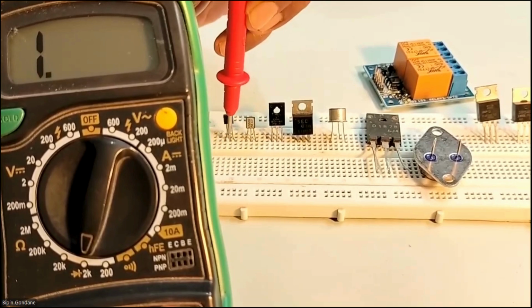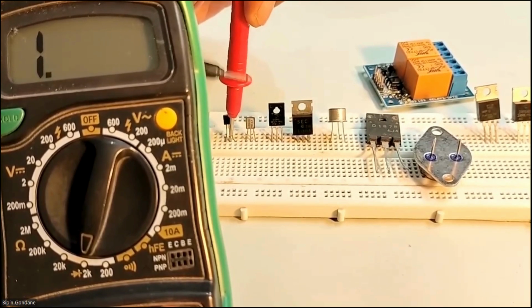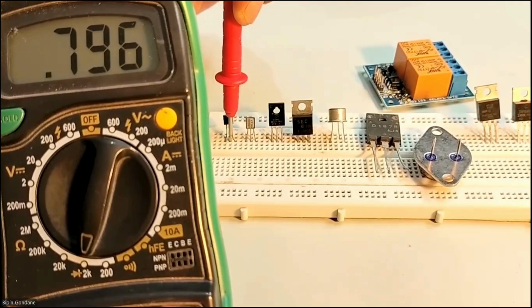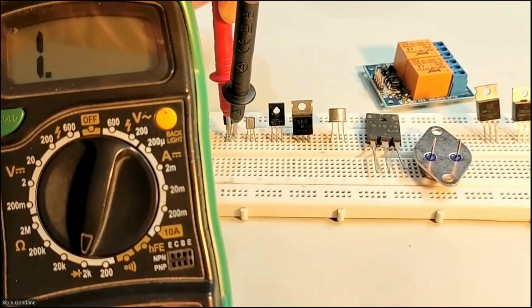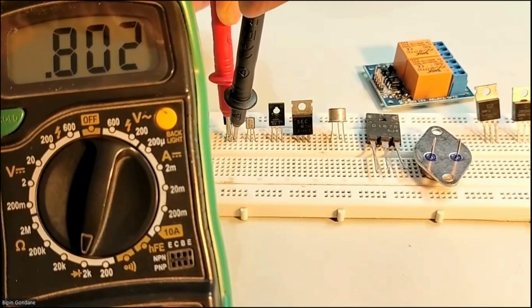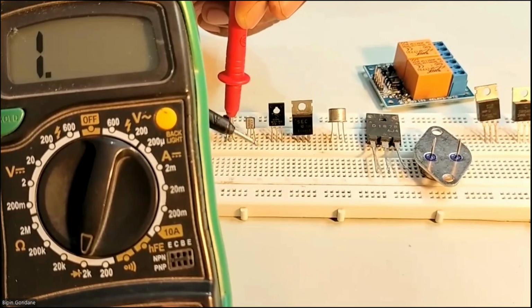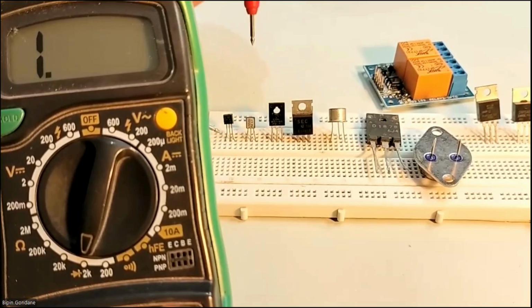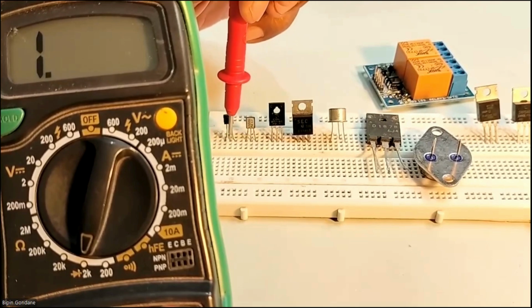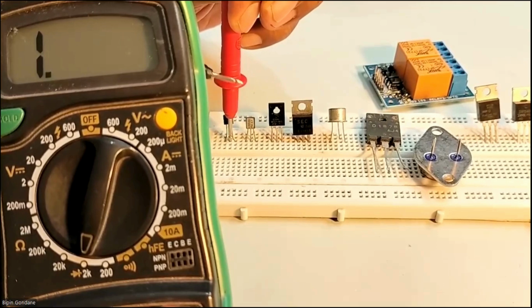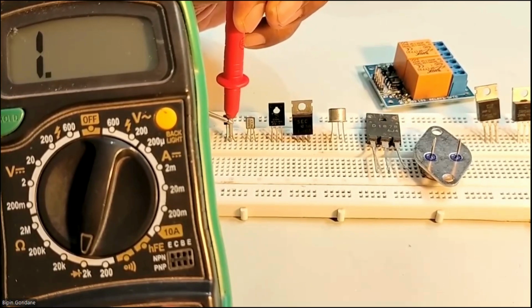When the positive end, this is positive, P, and this is negative, when it is kept here, we got the value. And the same thing happened on this side also. So what is this transistor and what are these points? Please remember, this is negative, that is N, this is P, and then again N. So this is an NPN transistor we have checked. Likewise, you can test an NPN transistor. Where I have kept the red or the black, that will be my base.